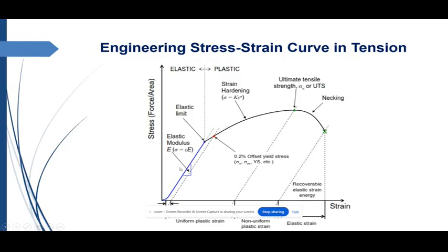Stress increases with increasing strain up to the elastic limit in a linear way. This is the elastic limit. After that, this is your yield stress. This is elastoplastic deformation. Here the stress increases with increasing amount of strain. This is according to strain hardening.